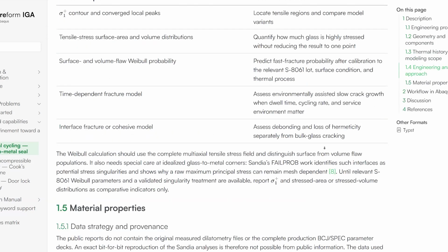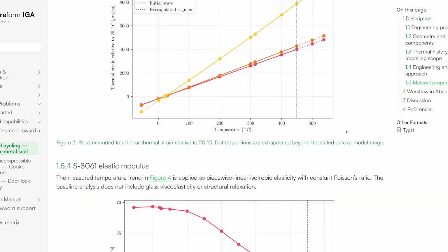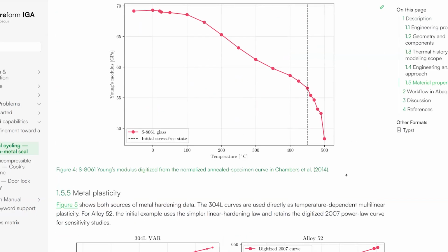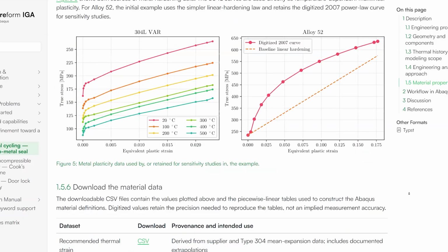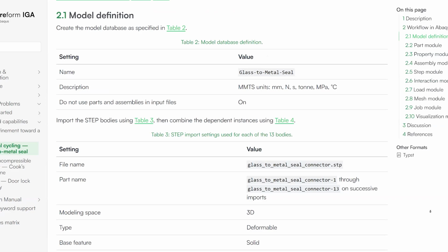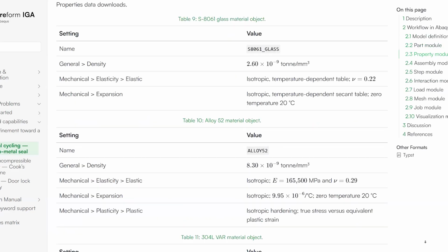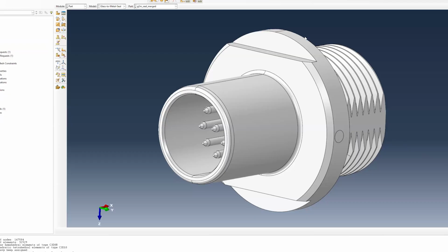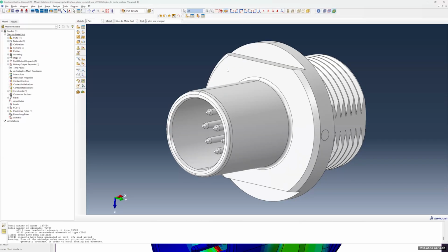But what I want to point out is that there are complex material models. There's thermal expansion, that's temperature dependent thermal expansion, temperature dependent Young's moduli, temperature dependent plasticity models, that because we use UEL and UMAT, those are all available to users to test out. So to clarify, I just want to reinforce that this demo is going to demonstrate beta functionality that's beyond the release functionality of linear static stress.